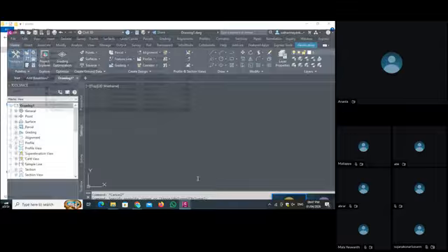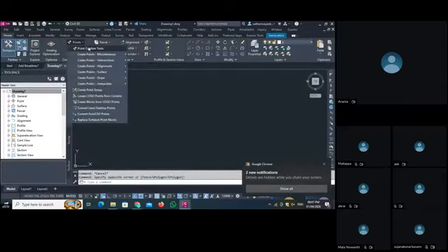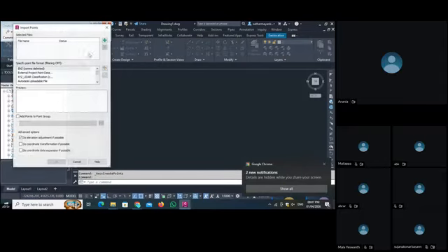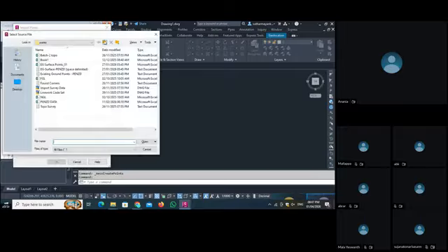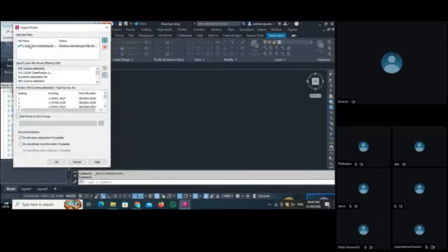So what you do is import the points from the point creation tool. Click on the Add button. Click on topo survey. Then open it. As we open, we see here a green check, so it means it's imported properly. Then you have to select the file format, and check in this preview whether it is as per your file format or not. If it aligns with your file format, then you set OK.